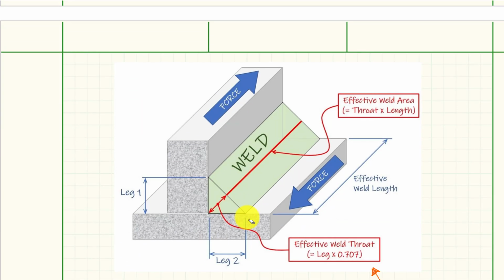We're going to apply a lot of the same thought process to a weld. In a weld, typically we have one member going in the opposite direction of the other member. So we have these two pieces not connected right here, but connected through a weld, and the weld's going to have an even leg on this side and this side. If we use basic trig, we can calculate that this is going to be a 45-degree angle, and if we take the sine or cosine of that, that is going to be 0.707 over here. That's going to let us get the effective throat on this.